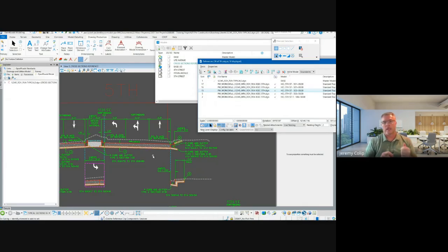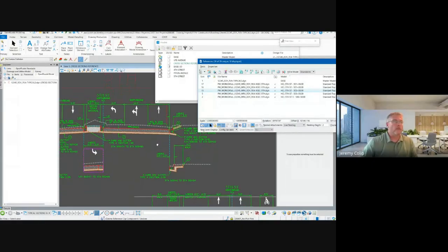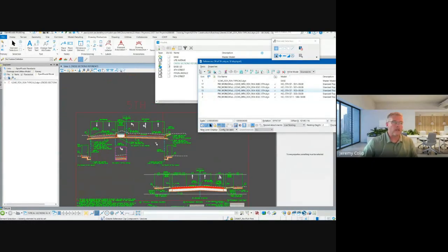But one of the good things about it, again, is that it's one source of truth. I updated my corridor. It told me my sections are out of date. Now I need to update my sections because I have all these dimensions that don't associate with anything anymore. So it's kind of a check on its own, and it makes me look for those things as I'm doing a quality check, a QC, on information. This says, hey, something's not matching up, something's not right, you need to fix this. So that's another reason that we do that. And again, it's dynamic, where things change and things update.